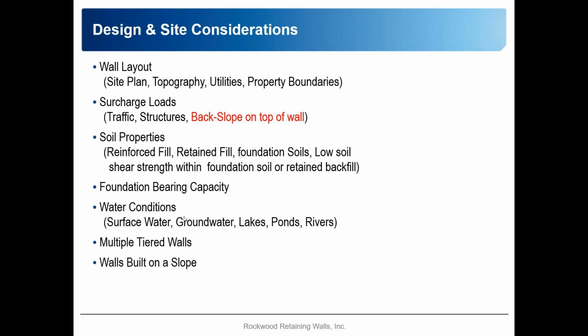Sometimes they're obvious, sometimes they're not. In a residential type application, the things that are potentially going to introduce or add water are gutters and downspouts, things that would potentially be directed at the retaining wall. You're going to want to address those, water capture areas, and get it out around the wall by extending it with solid drain pipe or something like that, keeping water away from the walls.